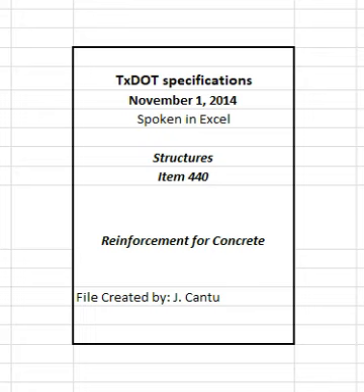Use mortar or concrete with a minimum compressive strength of 5,000 psi for precast bar supports. Provide a suitable tie wire in each block for anchoring to the bar. Place individual bar supports in rows at 4 feet maximum spacing in each direction. Place continuous type bar supports at 4 feet maximum spacing. Use continuous bar supports with permanent metal deck forms.